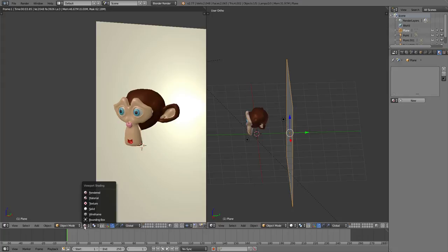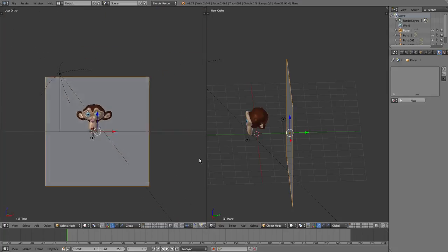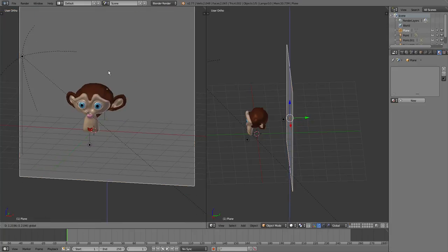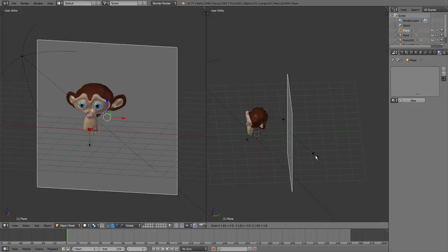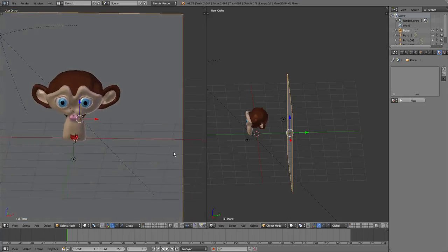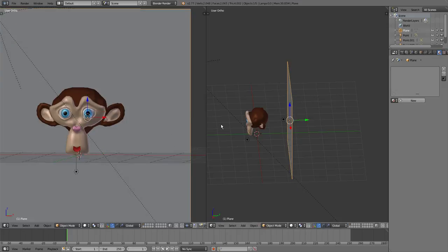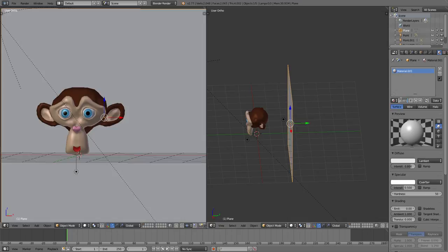Now I'm going to turn off this renderer because it's just kind of screwing up my CPU with this recording. Let's shift it up a bit. Maybe we can probably scale this down by 0.8. So we want to nicely zoom in like that. Okay, so let's go new material.